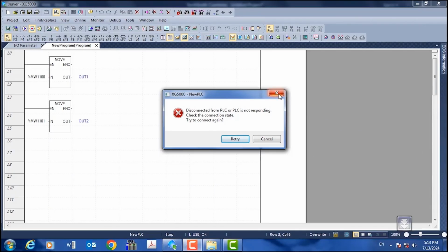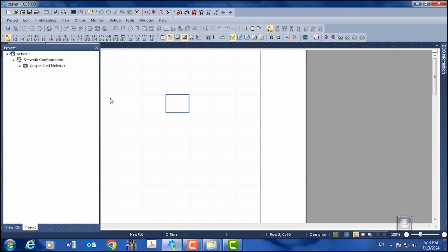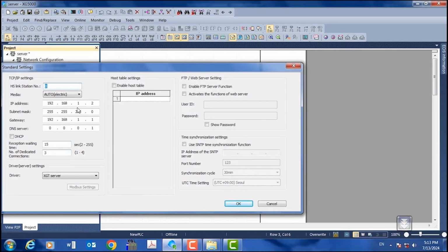All right, now let's move on to the PLC server program. For the PLC server, we've specifically chosen a compact U-series PLC, which already comes equipped with a built-in LAN port, so there's no need to add an additional network card. What we need to do next is the settings related to the PLC itself involve an FENET module. We click on that, and through this section, we can configure the network settings.